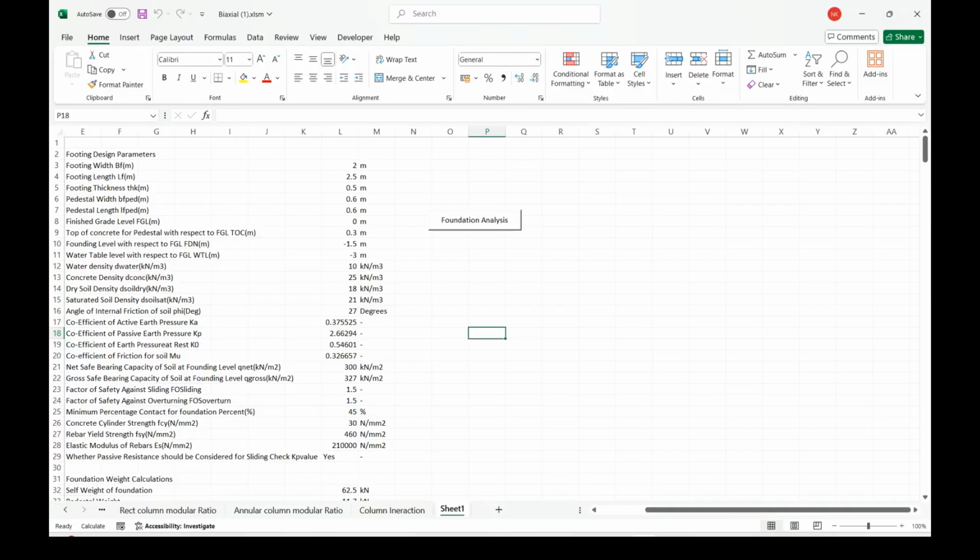In our last video 1, the link for which is provided in this video, we introduced how we can automate the solution for a rectangular footing subjected to biaxial bending and an octagonal footing subjected to bending. In actual design, there are multiple load combinations for which the following checks should be carried out for an individual footing. Check the foundation against sliding and overturning with an appropriate safety factor, say 1.5 or 2.